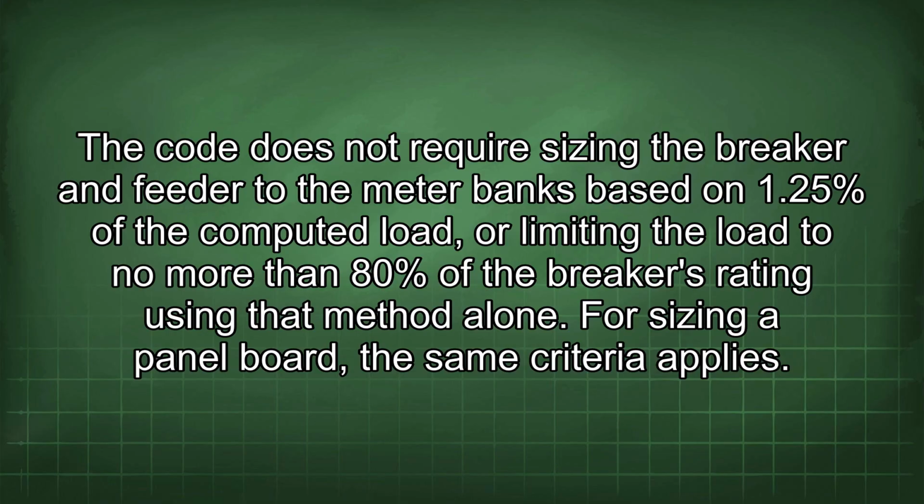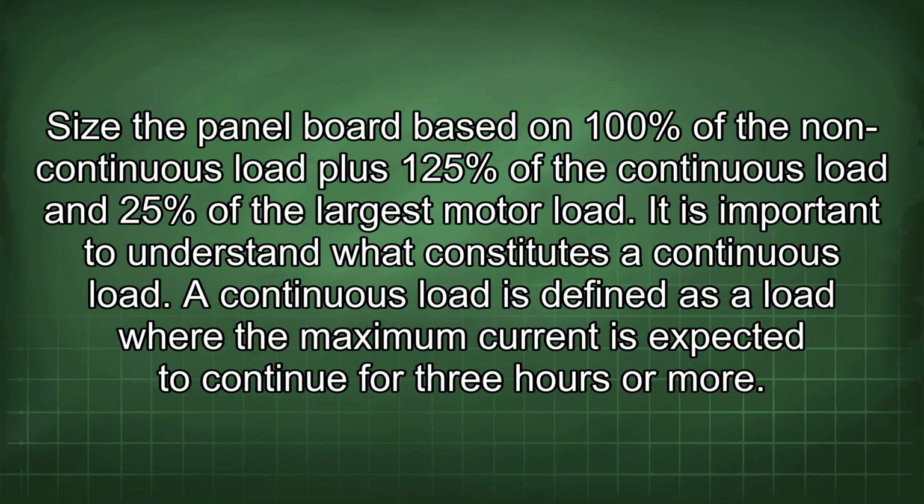For sizing a panel board, the same criteria applies. Size the panel board based on 100% of the non-continuous load plus 125% of the continuous load and 25% of the largest motor load. It is important to understand what constitutes a continuous load.